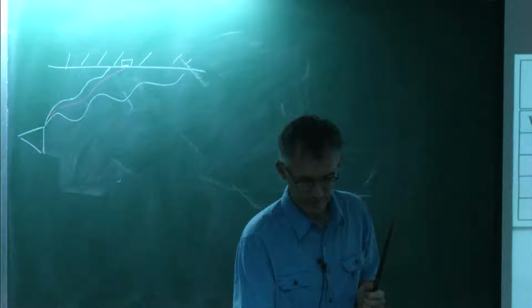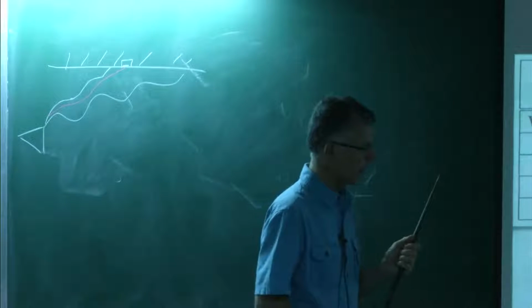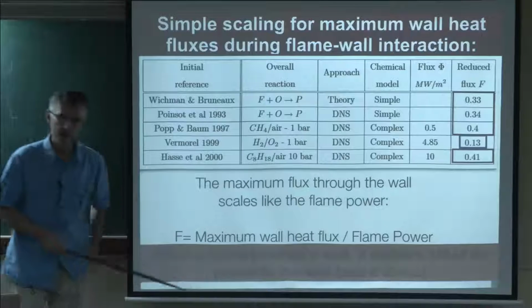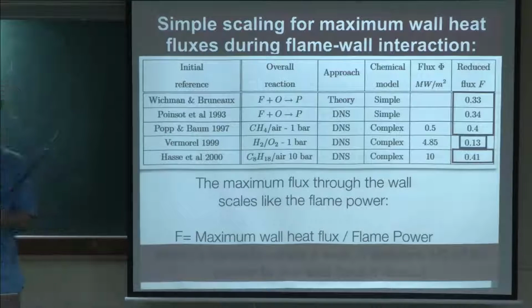So there's a very simple rule you can keep in mind: when the flame touches a wall, it will deliver approximately 1/3 of its power to the wall. And then it will die. Okay. That's the important message there.